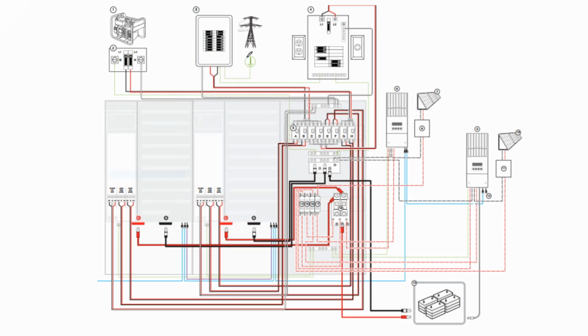At that point, you can land it between the grid and your service panel. That's actually part of the National Electric Code: the backup system has to be capable of supplying the loads on the backup panel. So you can't just put a 200 amp service panel and supply it with a 1 kilowatt backup generator.